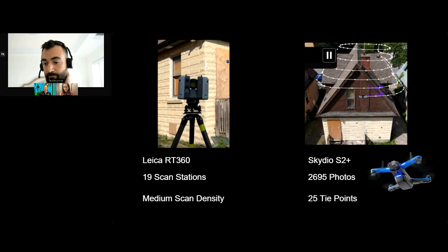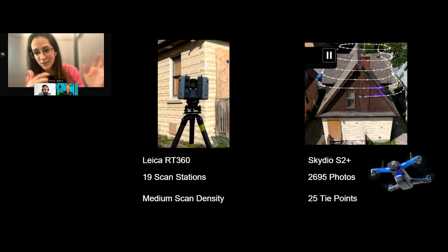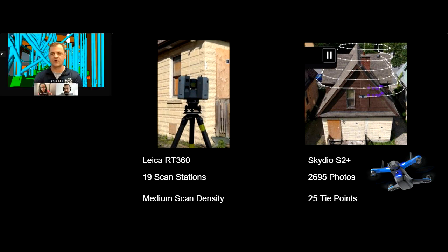I expect that for certain projects that's already an advantage of photogrammetry versus LiDAR. After the flight and the processing, you already get a representation of your physical asset, which you do as well with LiDAR, but you don't have that color in your final 3D model. You do have the option with LiDAR: you can add the photograph after, and then each point will have the RGB value. But it's an extra step after the data capture.